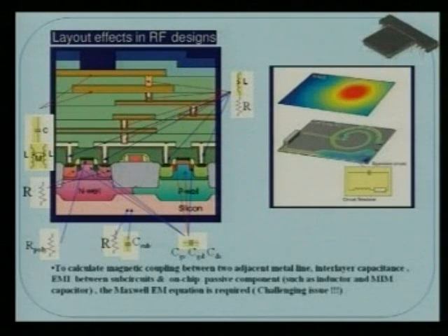And the top metal layer is made exclusively for fabricating the inductor and the capacitor, because it is a little bit thicker, so that its resistance is less. You know, the thicker conductor offers less resistance, and therefore it is used as the passive component layer for making inductors, etc. For example, one inductor you have seen, how it has been fabricated. Now, if you look at that 6 metal 1 poly 1 AP layer process, 0.18 micron standard CMOS process, then how this simple inductor or simple connectors become complex.